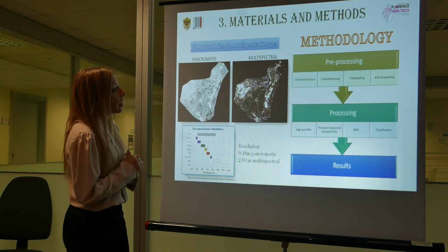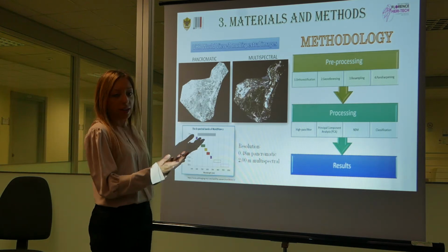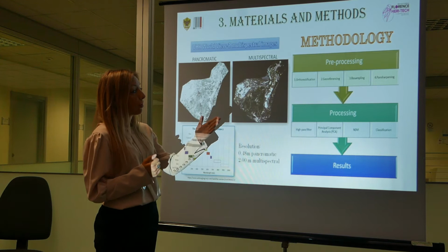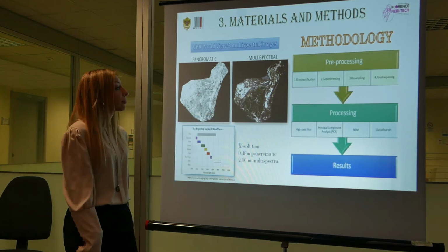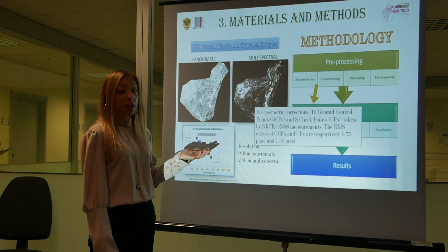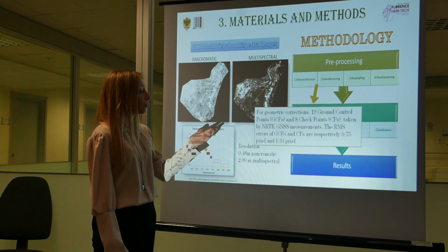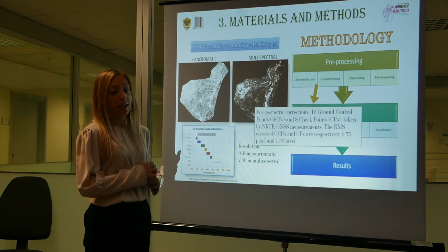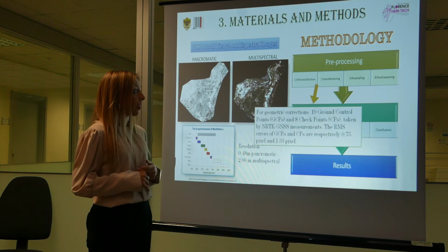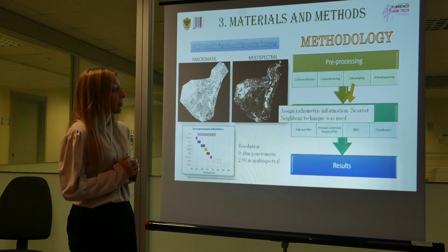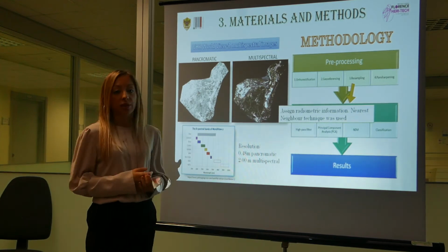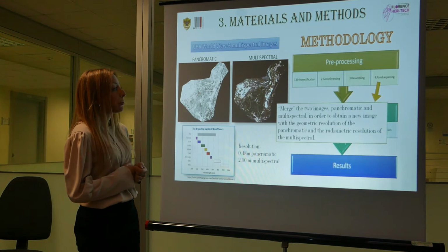About the methodology, we performed, as for all satellite images, a pre-processing, which consists of orthorectification, georeferencing, resampling and pan-sharpening. Orthorectification and georeferencing are useful for geometric corrections. We made NRTK GNSS measurements to take 19 ground control points, GCPs, and 8 checkpoints. After that, we performed the resampling in order to assign geometric information, and we used the nearest neighbor technique. In the end, we performed pan-sharpening.